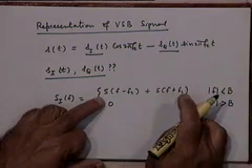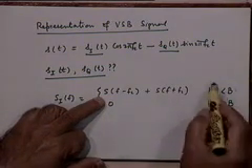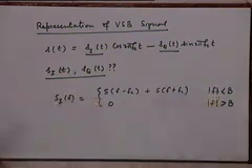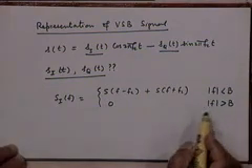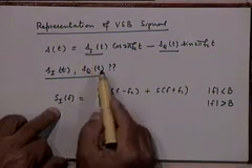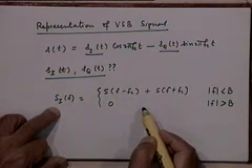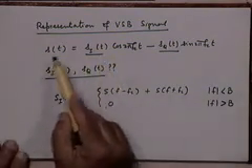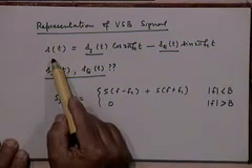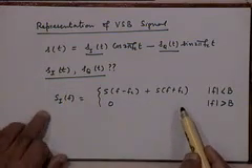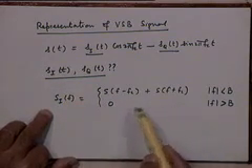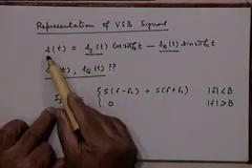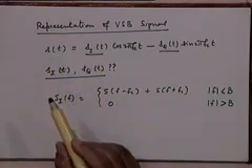This has two regions where it is non-zero. It is non-zero in this region and it is non-zero in the region around 2fc. That portion is being cut off by the low pass filter, and therefore the spectrum of s_I(t) that you have in this representation must be given by this expression. Are you all with me? Because you can see that s_I(t) can be obtained from s(t) by multiplying s(t) with cosine 2 pi fc t and passing the result through a low pass filter, and that fact leads us to this expression for the spectrum of s_I(t) in terms of the spectrum of s(t). Any questions on that?